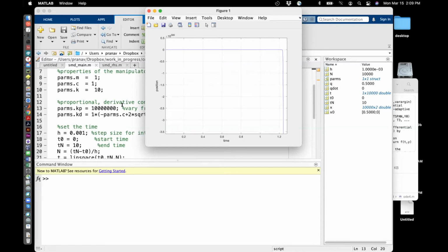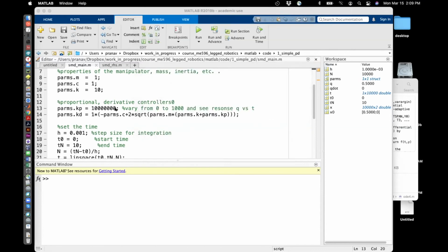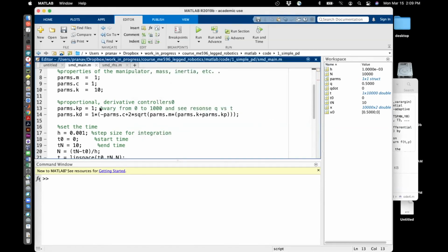On a real system, you cannot have a high gain because you invariably have noise. So your noise is, let's say, on the order of 1e-3. At some point that 1e-3 is going to get multiplied with a gain of 10,000 and become like 1. And that's where you'll realize that instead of canceling the errors, you're actually amplifying the noise, and then you will have an unstable system. So this limit is basically set by your system, typically the noise, and sometimes even the disturbance and modeling error. This is just an illustration of what you can do with a simple system and have an intuition about feedback control.